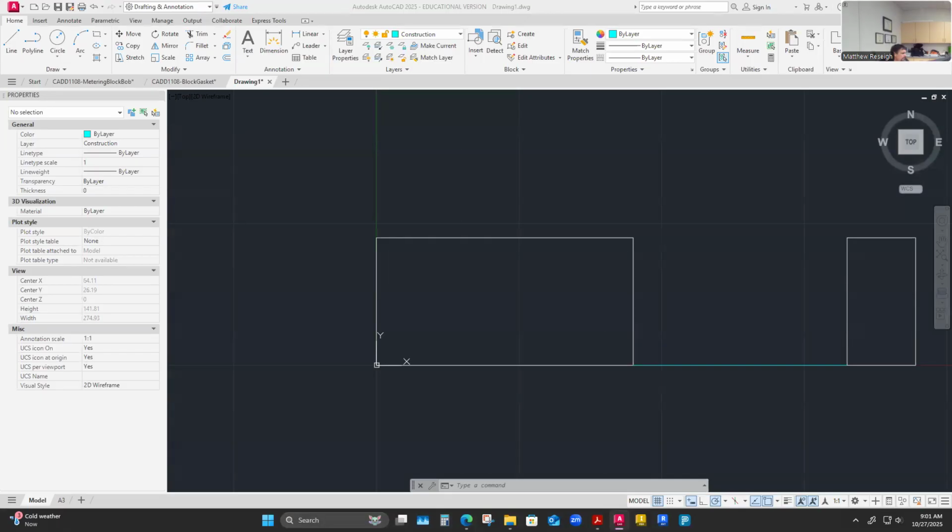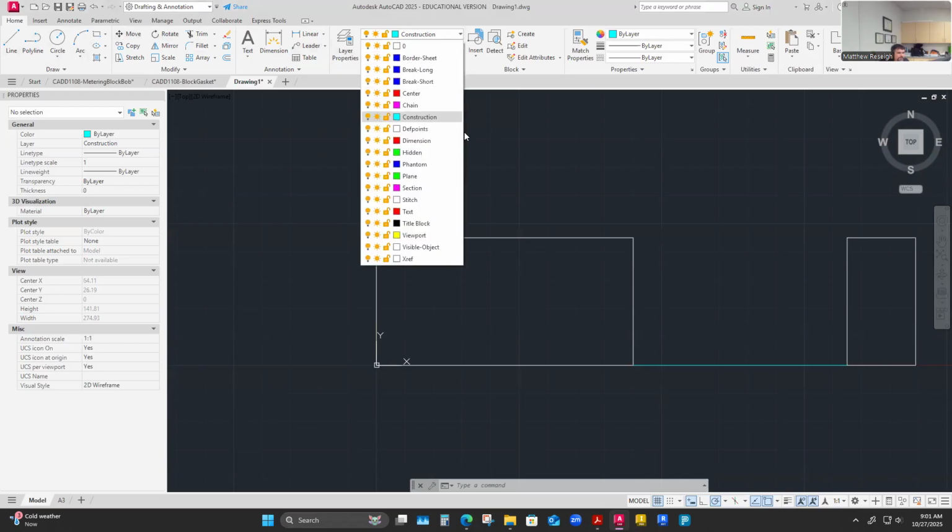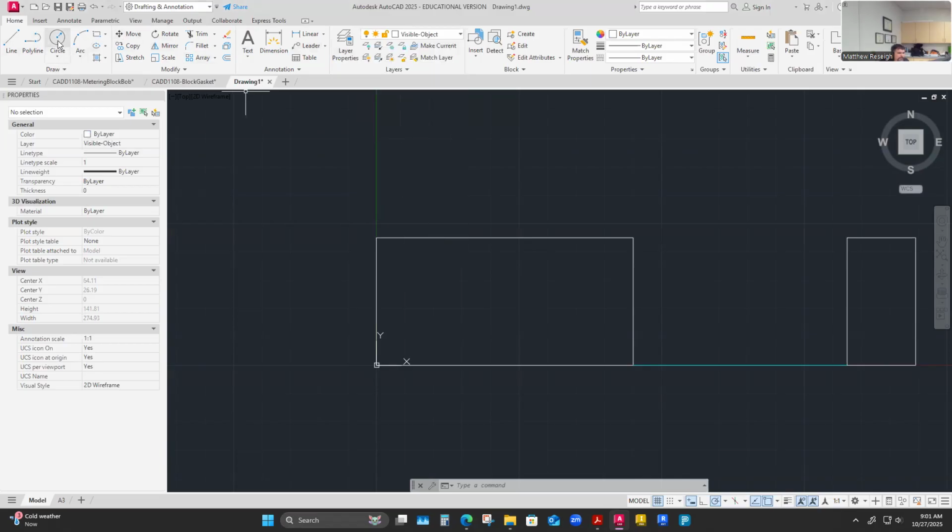Maybe if I get my thing positioned right. There we go. I'll get on my circle command on my actual visible line layer. I just got to go place all these circles by coordinates. So you remember, just like a line, I have a coordinate point here for my circle. Center point of the first one, A, is 64, and this is X, Y. My cursor's first box is X, the second box is Y coordinates. So I should be able to type them in just like they are in my table.